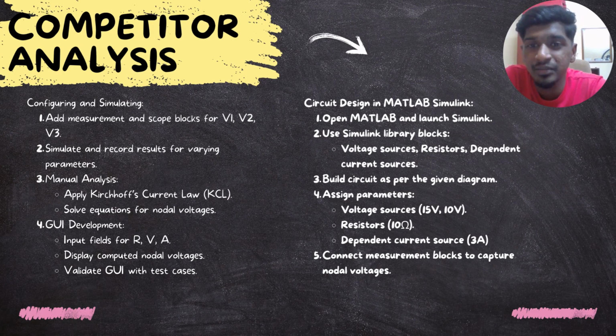First step is add measuring and scope blocks for V1, V2 and V3. The second step is simulate and record result for verify parameters. The third thing is manual analysis, such as apply Kirchhoff current law and solve equation for nodal voltage.